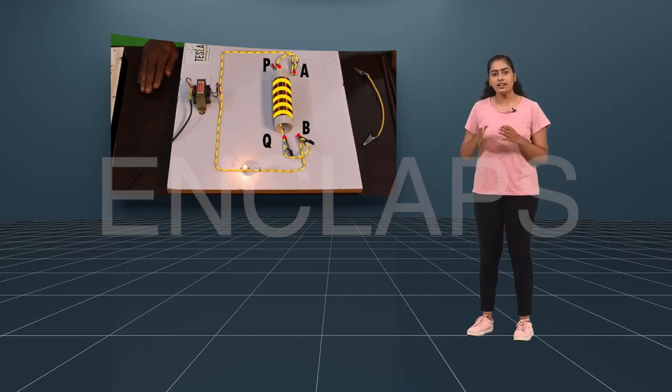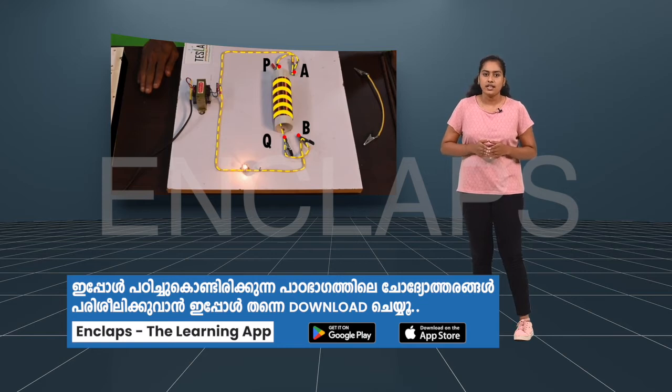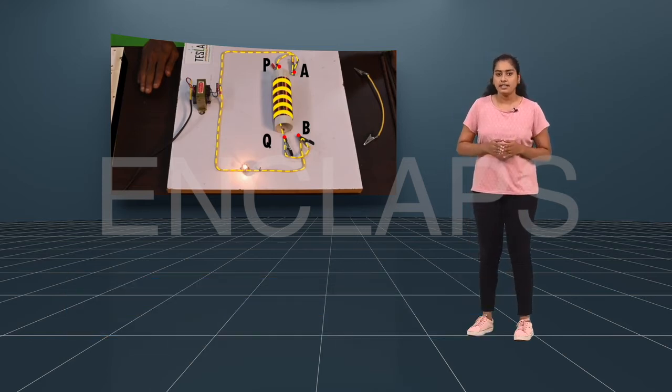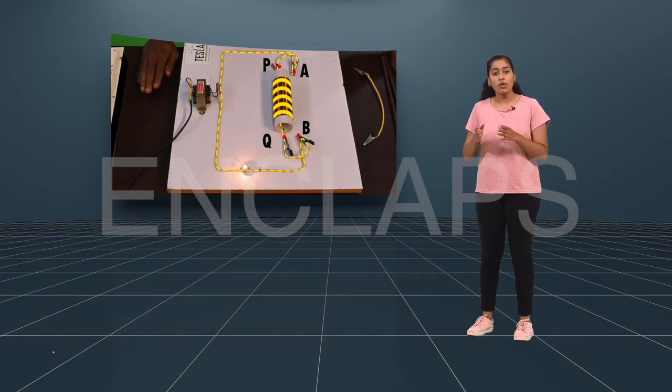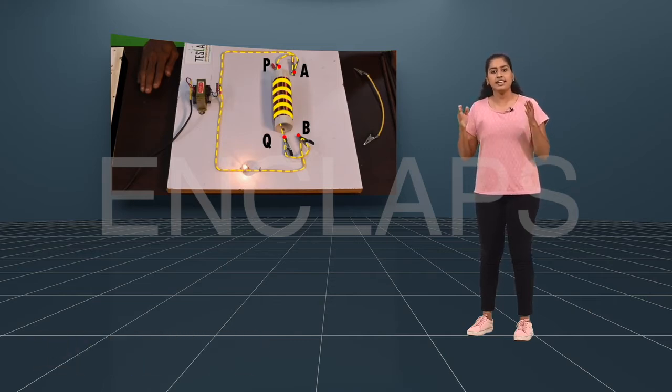How does the solenoid reduce the intensity of the bulb? We can say that some changes have occurred inside the solenoid. Since AC is passing, the direction changes 100 times in a second. When AC passes through the solenoid, it acts as an electromagnet. The polarity of this magnet also changes 100 times in a second. As a result, the direction of magnetic field lines is changing 100 times in a second. So, the solenoid experiences a change in flux and hence an EMF is induced.